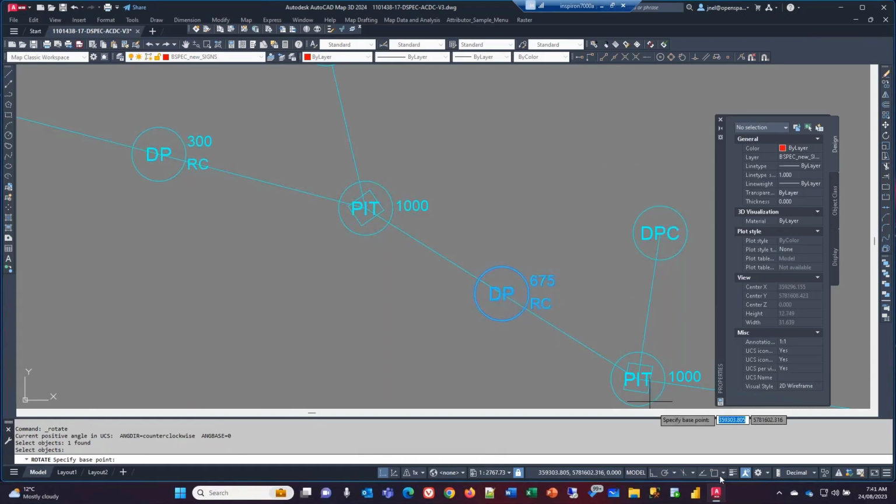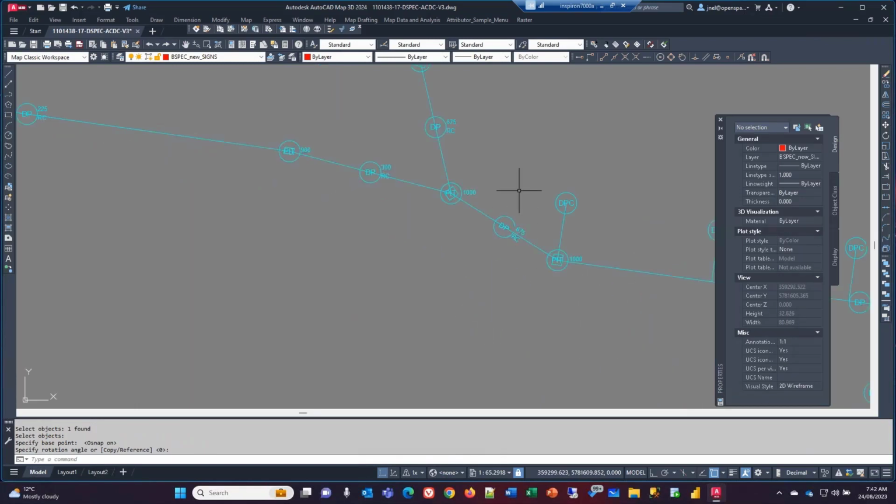Now I'm going to turn my snap mode on there, and here you can see all of those. So insertion is one of those that's turned on. So let's turn that on, and say, okay, insertion point there, and snap to that one. So now it's picked up that rotation, and it will then display that for me. So quite easy to actually place the rotation programmatically.